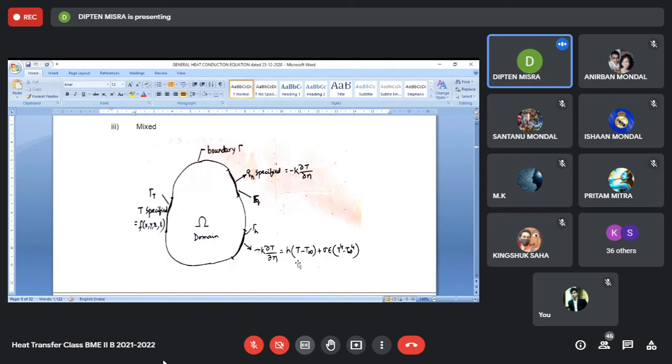This is something you can always specify if there is heat loss by radiation and convection. So this is a boundary condition we specify when the temperature on the boundary is not known. And also, if the heat flux is not known and the temperature gradient is not known, then we can live with this very general prescription of boundary condition.